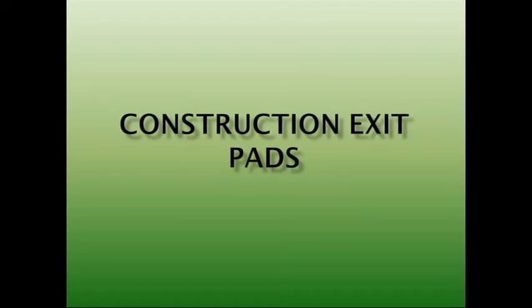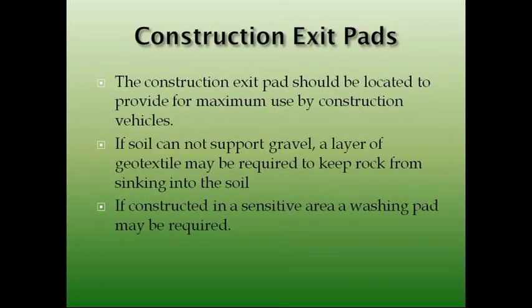Construction exit pads should be located for maximum use by construction vehicles. If the soil cannot support gravel, a layer of geotextile may be required to keep rock from sinking into the soil. If you're in a wet area, make sure you put some type of geotextile down. It's a good rule of thumb. It's not going to cost you a lot of money. It will end up costing you a lot more not to put this geotextile down and then have to keep adding rock. So make sure that geotextile layer is there.